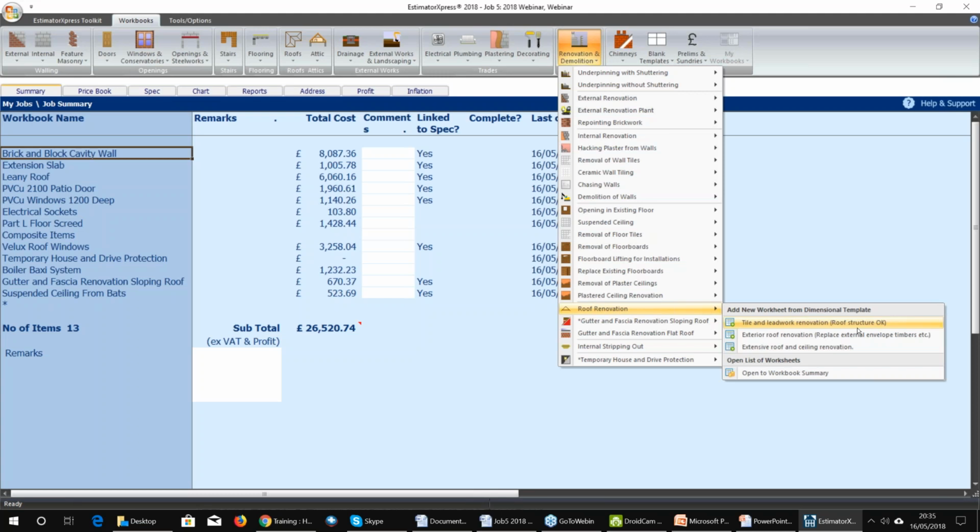The battens could be fine or newer, in which case they're actually going to be an absolute pain in the neck to get off anyway, because a really well hammered down batten is a pig to get off. Or you could have trouble getting across the roof anyway because the battens are so rotten that as soon as you try moving across them, they fall off their nails and you end up stabbing yourself on the nail through the palm. I can speak for that from experience.